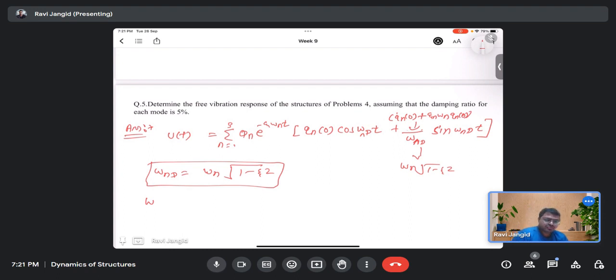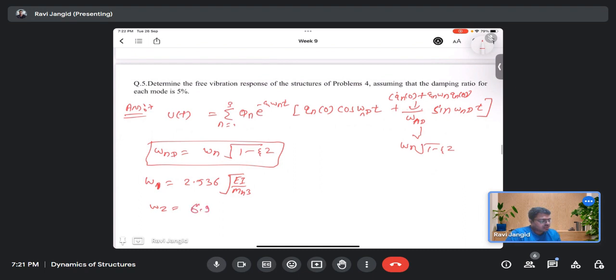So you have the omega d. Omega n I can write for you again: omega 1 is 2.536 square root of EI by mh cube, omega 2 is 6.9282 square root of EI by mh cube, and omega 3 would be 9.641 times square root of EI by mh cube.